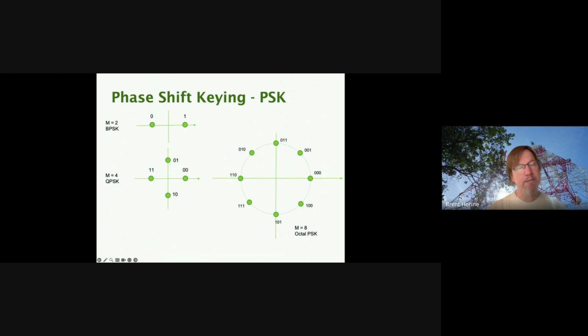So when you have that constant envelope, that is much easier, much cheaper, much more efficient in terms of power to build a power amplifier. And when you put something up into space, power is everything. It's really hard to get enough energy in these things. And also, if you're not efficient, the power that you put in that doesn't come out, because you're not very efficient, is dissipated as heat. Well, in space, it's really hard to get rid of heat because you don't have any airflow moving across your components. So heat dissipation ends up being a really big deal.